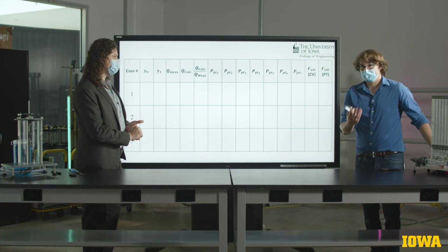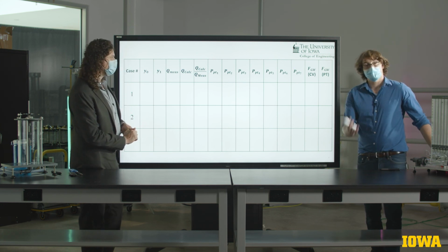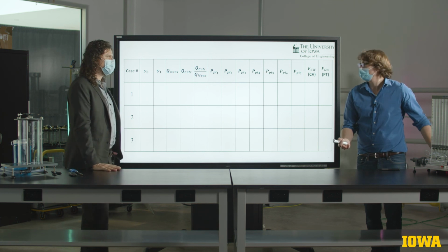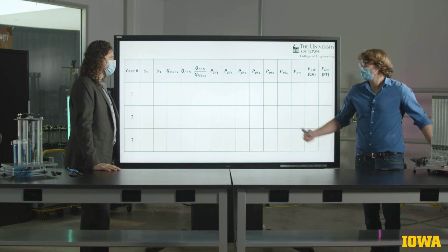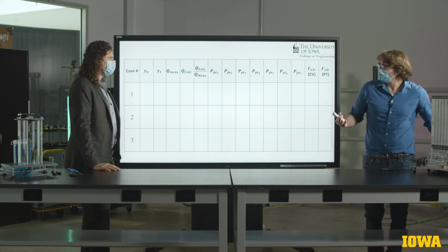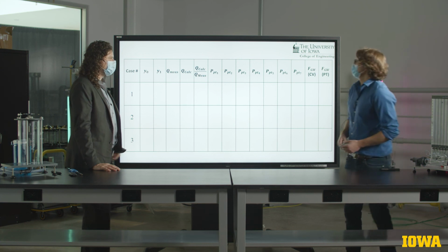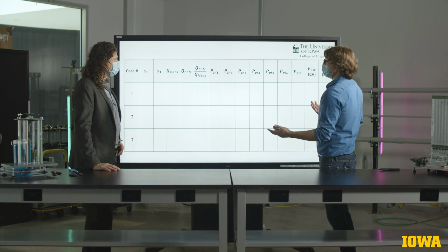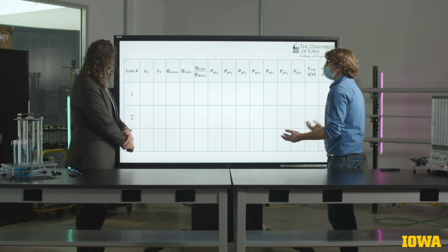So just as in previous analyses, the task is left up to you to find your sensitivity coefficients from the data reduction equations and to propagate those elemental bias limits through to the final answer. Once you do so, it's useful to present your data in a summary table like this.